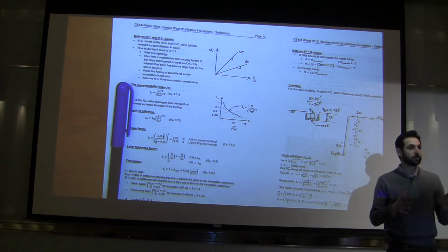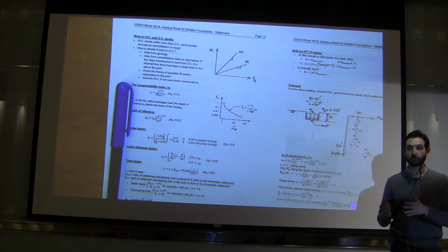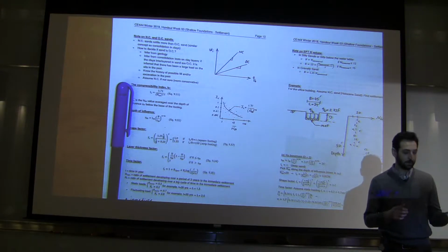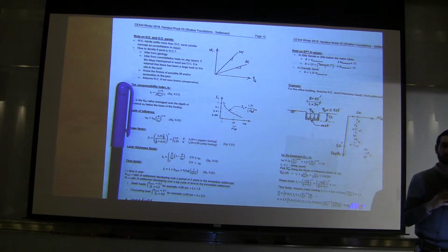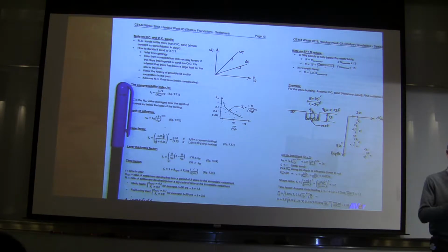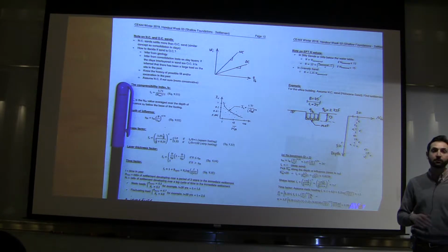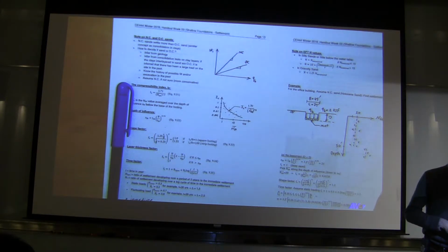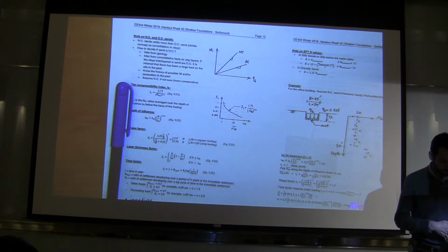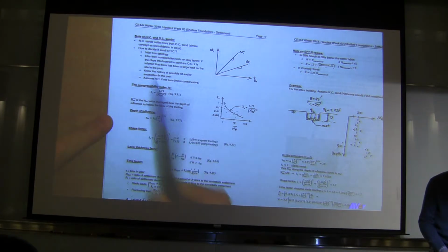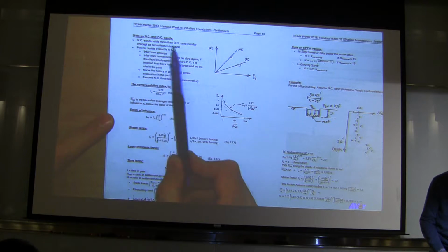So again, we define normally consolidated or over consolidated usually for clays. But it turns out that sands could also be normally consolidated or over consolidated. And it usually doesn't matter, except that in settlement calculation it does matter. So what does it mean for a sand to be normally consolidated? Let's go through all these bullet items here. NC sand settles more than OC sand.